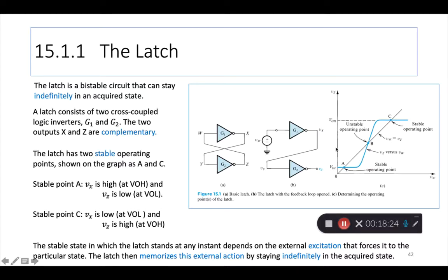Now this terminology, output low, output high, we get it from our study of CMOS inverters, right? OH meaning output high, generally that equals VDD or close to VDD. Similarly, output low is close to 0, you know that. So depending on whether it's a CMOS inverter or a MOS inverter, the quality of VOH and VOL, we have studied those.